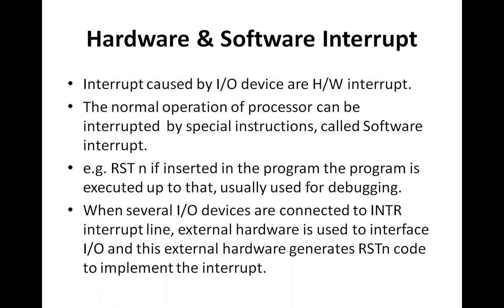Normally, the use of RST instruction is applied while doing the debugging of the program, as well as the internal abnormal or unusual conditions which prevent the normal processing sequence of a processor, which are also called exceptions. For example, if while executing a program, we come into a situation that is divide by 0, which is going to cause a problem, it is an exceptional case.